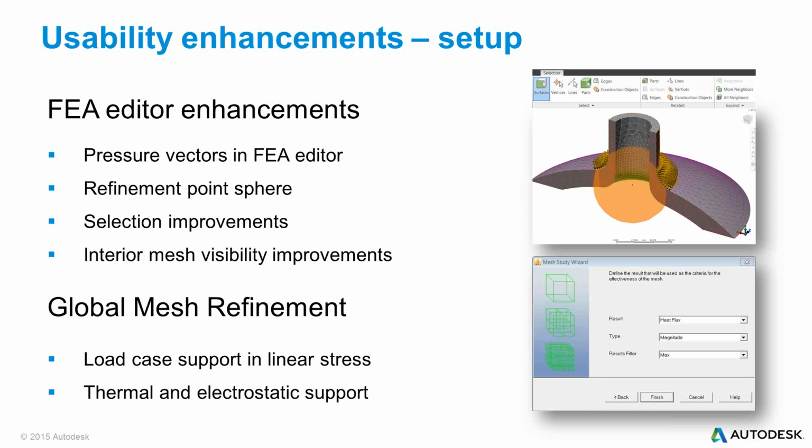The Mesh Study Wizard, which automates this process by creating multiple design scenarios with various global mesh size refinements, and displays a convergence plot. So in this release, the Mesh Study Wizard has been enhanced to support different load cases for static stress analyses. It has also been extended to cover thermal and electrostatic analysis types.